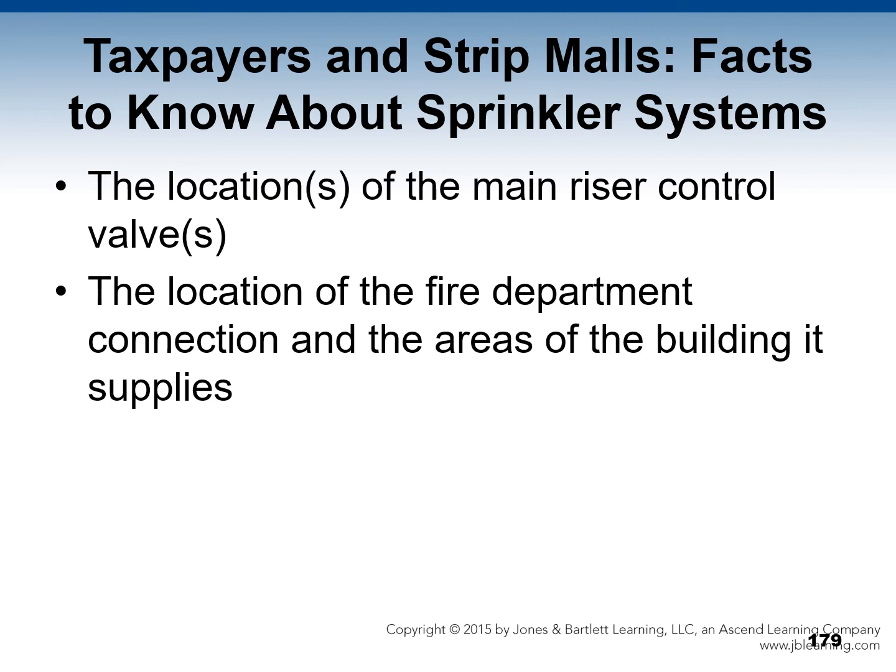The location of the fire department connection needs to be known, as well as the areas of the building that it supplies. And also in pre-incident planning inspections, you need to, among all these other things I've talked about, you also need to be aware of the closest hydrant to the fire department connection.